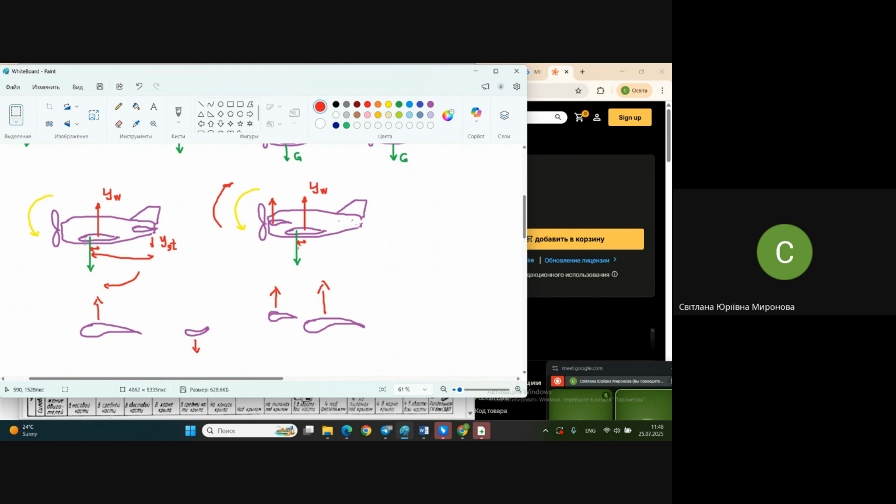The longer, the better. Because in this case, you may place less area of stabilizer. Less force is necessary because we need a balance of moments, you understand. The moment of the lift with respect to the center of gravity on one hand, and the moment of the stabilizer on the other side, with respect to the center of gravity. The more arm of moment, arm of force here, the less stabilizer is needed. Of course, that's better because the stabilizer is stealing the lift. In this conventional scheme, it's responsible for stealing the lift.